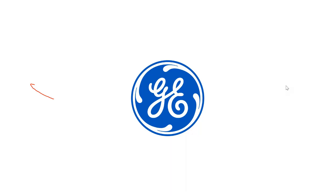So if the ratio at 4160 is 35 to 1, what would that be on the secondary? 120. So at 4160, you're getting maybe 118, say. Yeah, 118. So you'd set that to 118, and then if you wanted to set overvoltage, you would set overvoltage at 1.1 per unit.